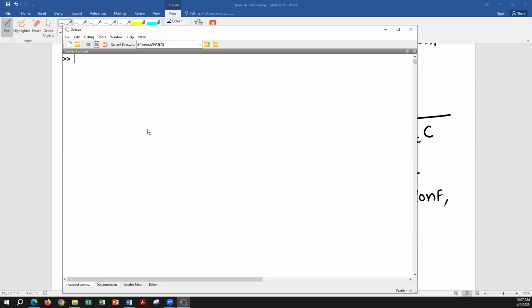So let's go ahead and define R is 3.18 exponent 3, C is 10 nanofarad. Those are two values of component. And then we're going to define, let's plot against f. So f is equal to, now if you're plotting logarithmic response, then remember log of 0 does not exist.